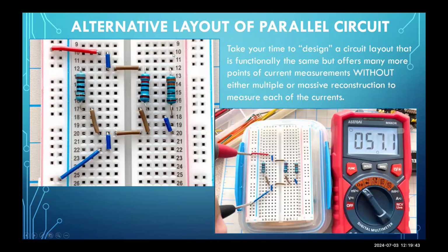Top of the resistors, are they connected on row 12 in my board? Yes, they are. They're jumpered together with this brown jumper, but they are all connected to row 12. Are they separated with this blue jumper from the red rail? Yes, this blue jumper represents a potential for me to pull out, create an open at the top of the bank. Remember, a nickname for a parallel circuit is bank.